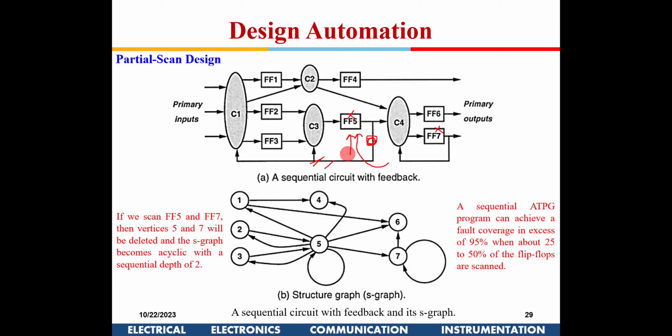So now the designer has to take a call whether he wants full or even partial is good enough. Okay, so partial, if in this entire circuit there are only a few flip-flops which are giving cyclic feedback, and it's not a very large VLSI circuit, in that case you might want to have just a partial scan flip-flop design also.